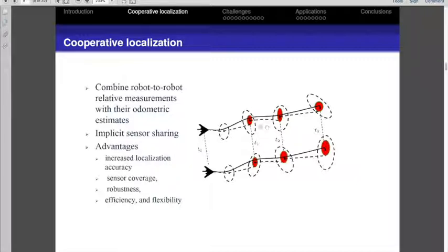But in this case, even though you are using range and even though these are better than just the IMU, they are still increasing. The red ellipses are increasing in size at t1, t2 and t3. So the idea is it is still unobservable. And it is unobservable because you're trying to estimate things in the inertial frame and there is no information about the inertial frame. So if this problem can be posed in a relative frame, you can make this system observable and you will not need any absolute information. So you can put this figure and then maybe you can talk about